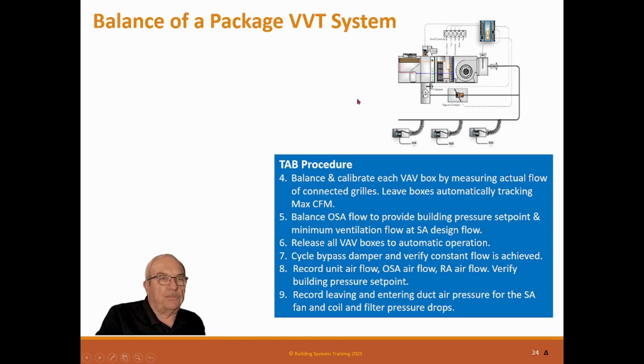So you're going to do a pressure profile of the unit, so you know what you've got to supply. You've got to measure the drop across the fan, drop across the cooling coil, drop across the heater, drop across the filters, and an entering pressure here.